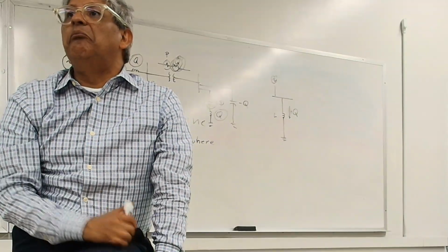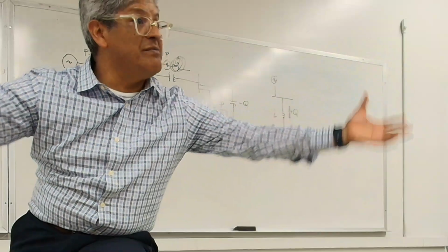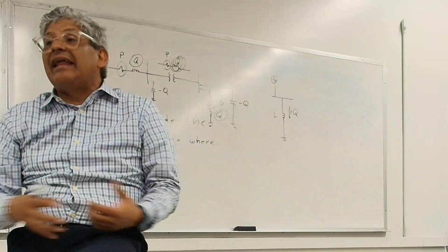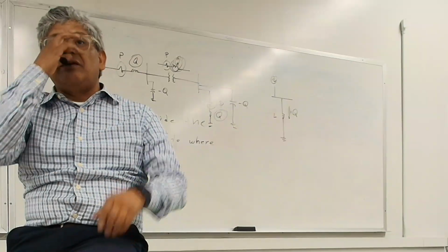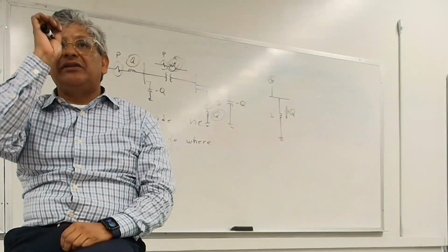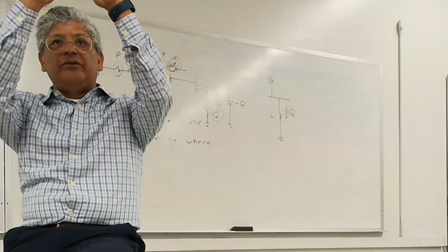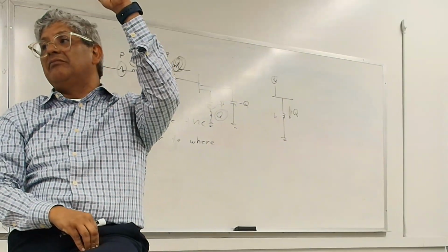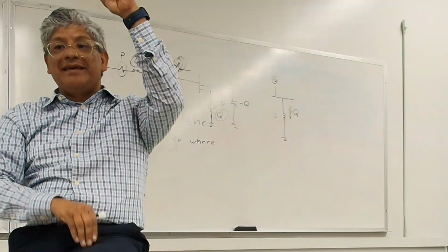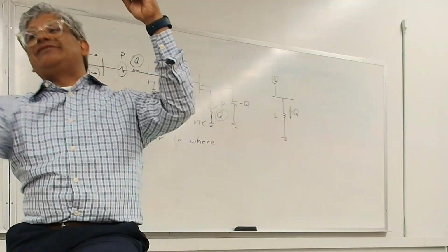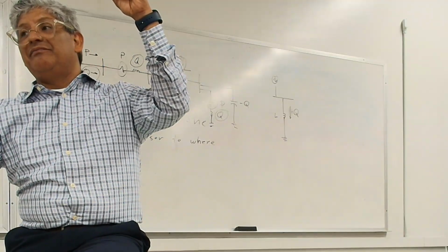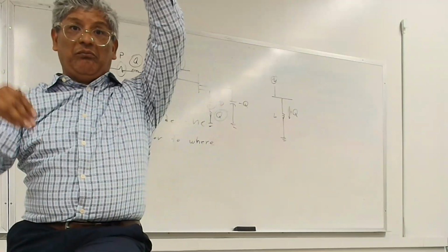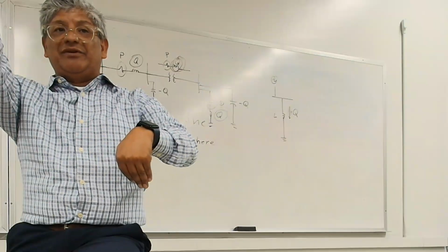So based on that idea, by agreement, power engineers said that's how we're going to analyze the system. We're going to freeze time and take a snapshot when the reactor is absorbing maximum reactive power. The capacitor is doing the opposite at that point, right? Providing the vars. So one is, I'm going to freeze it right there.